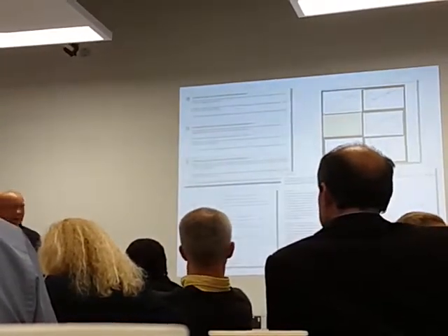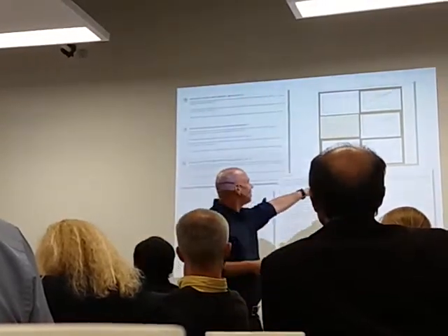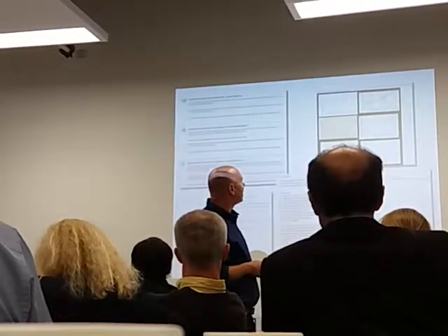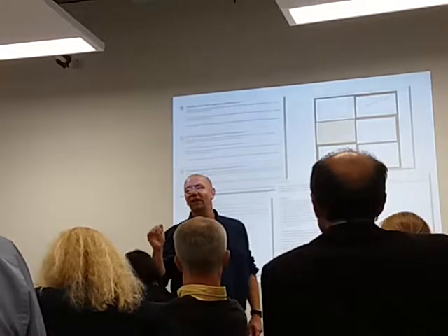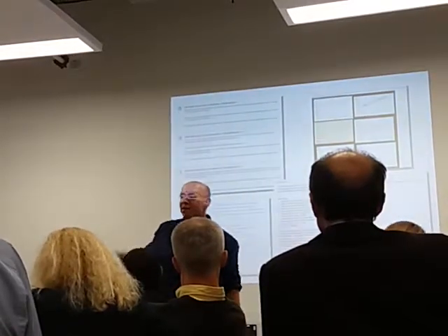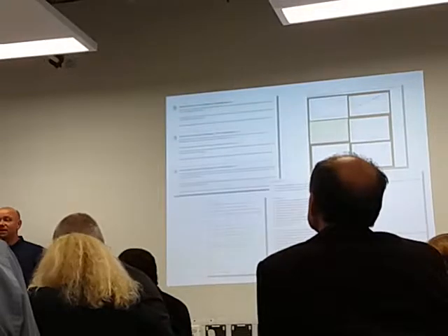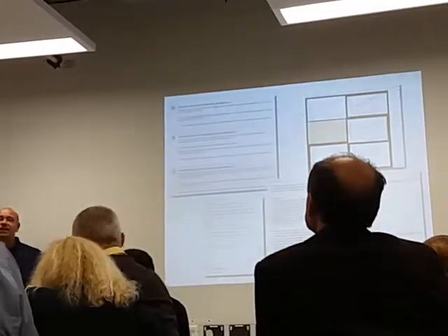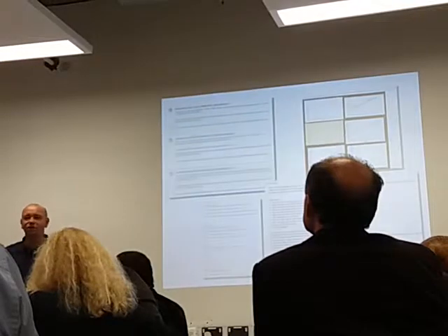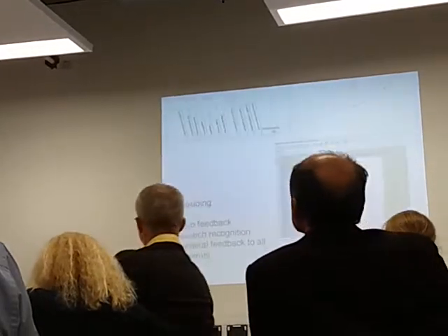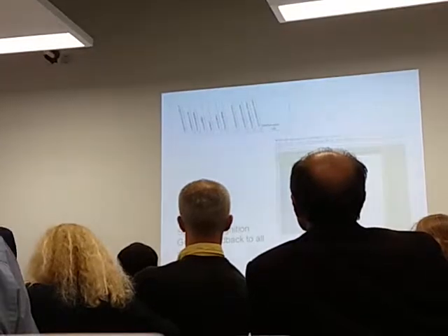In this case, they're being asked to look at a regression plot, so we've got the predicted versus the actual building energy demand, and they're asked to say which one of these shows air conditioning and heating running simultaneously. Something we have a lot of in the UK is everybody wants air conditioning, but it's not a hot country. So it's only internal building gains and things that drive air conditioning. The heating comes on because it thinks it's cold, the building gets too warm, the air conditioning comes on. So the students are getting a practical grounding in what really happens out there when they finish. And that's all part of the automated tests.